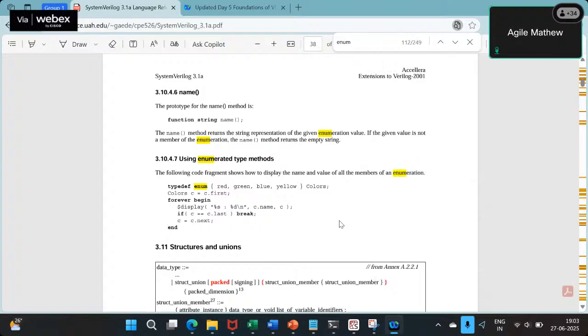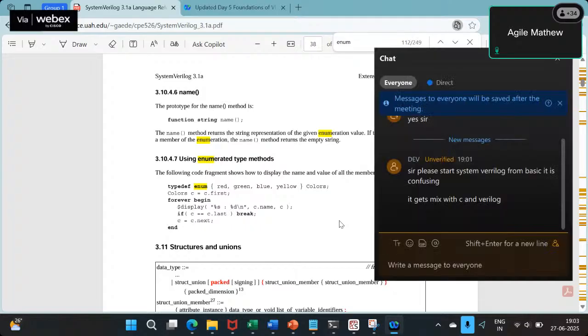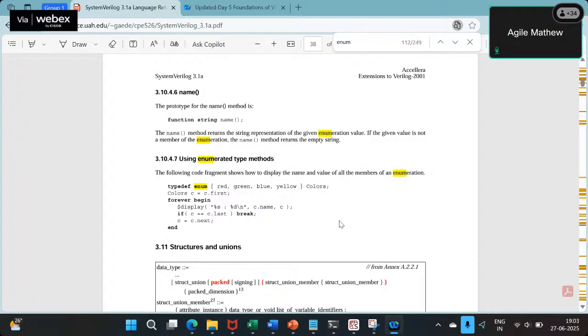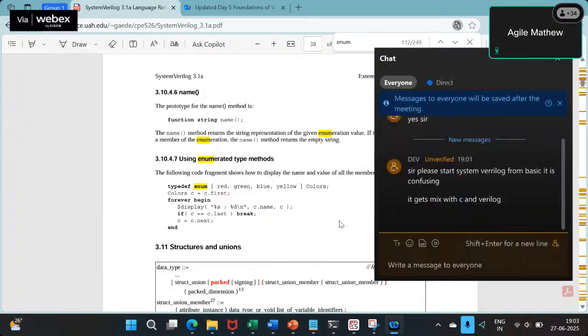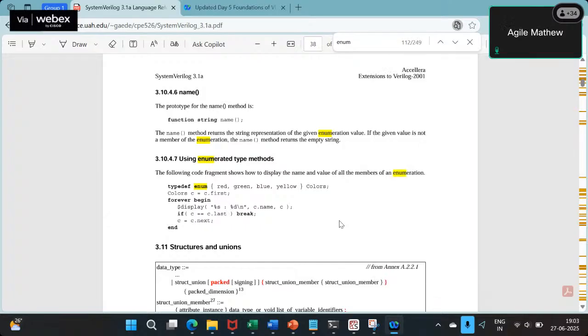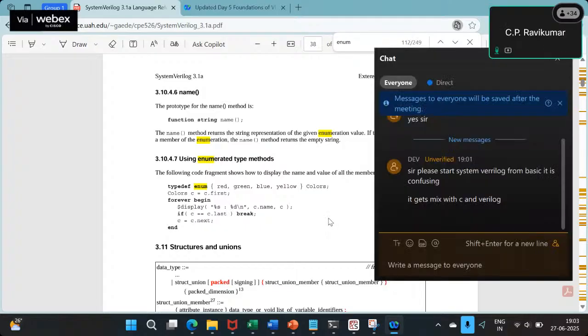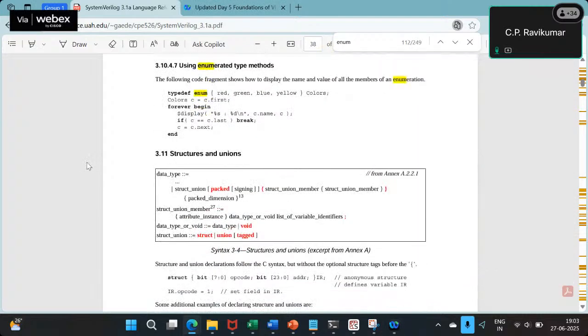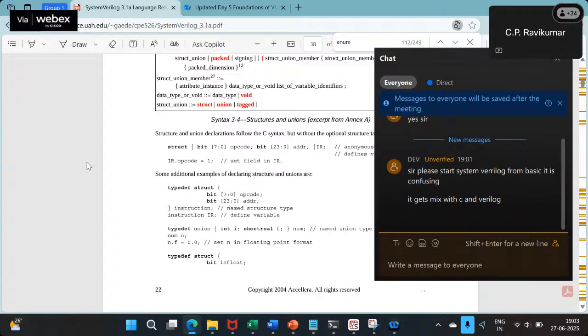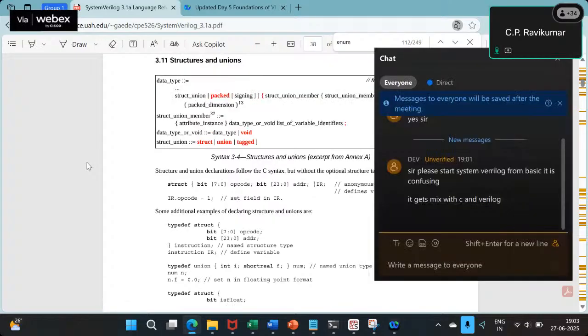We talked about, yes, for design we only use Verilog or we use System Verilog, and then for verification we use System Verilog. Is that right? But the System Verilog design is still not used for synthesis. Yeah, see, the kind of constructs that are there in System Verilog cannot be synthesized. They are mainly for making test benches.